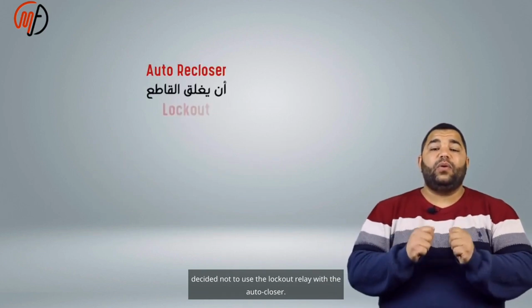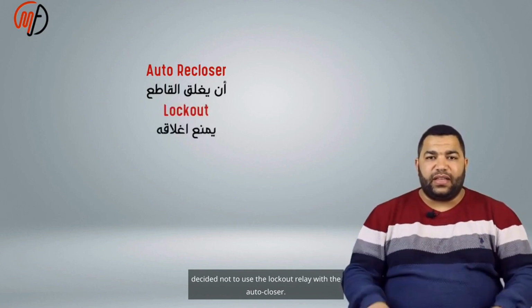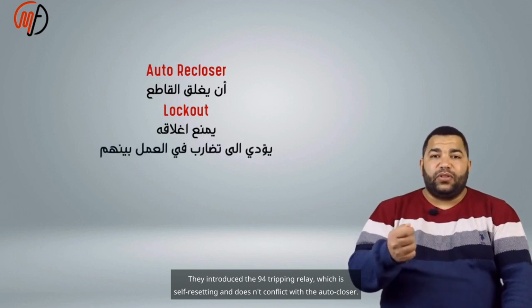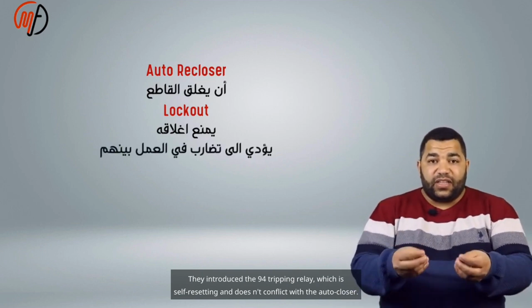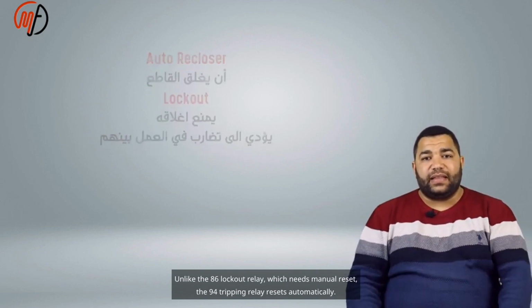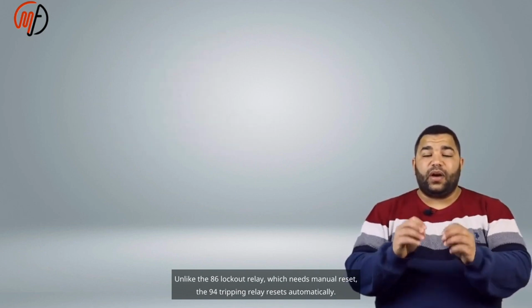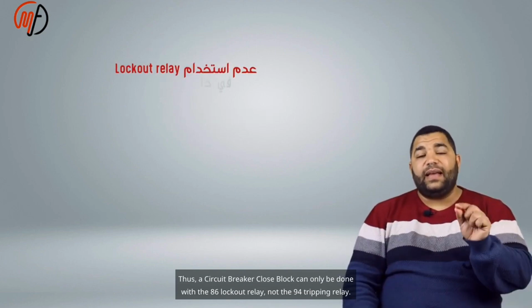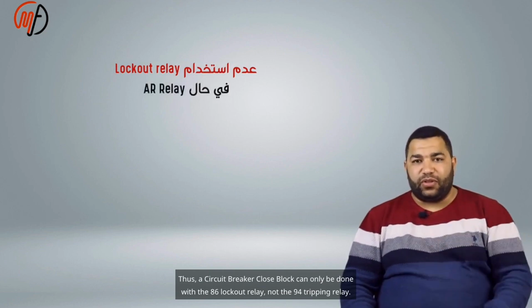Engineers decided not to use the lockout relay with the autocloser. They introduced the 94 tripping relay, which is self-resetting and doesn't conflict with the autocloser. Unlike the 86 lockout relay, which needs manual reset, the 94 tripping relay resets automatically. Thus, a circuit breaker close block can only be done with the 86 lockout relay, not the 94 tripping relay.